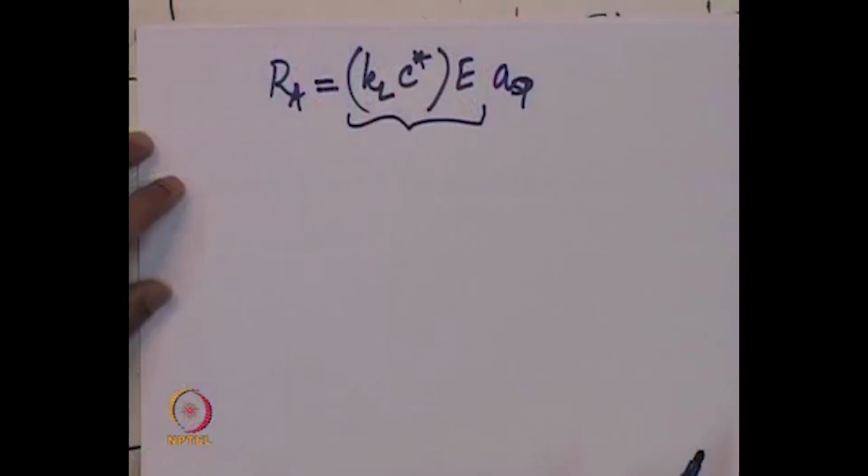The second thing that happens is that because the time of exposure is small, the depth of penetration is also small, and therefore, the surface element can be assumed to be infinitely thick from the point of view of the diffusing solute. So, we get to solve a partial differential equation of the second order, first order in time and second order in distance, in order to calculate the absorption flux in a single surface element as a function of the time it has spent at the interface. In order to calculate the average absorption rate at that location, we have to consider the unit gas liquid interface at that location, which itself is a mosaic of several surface elements of various surface ages.